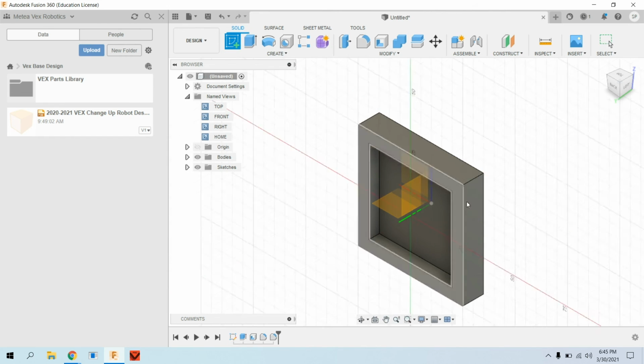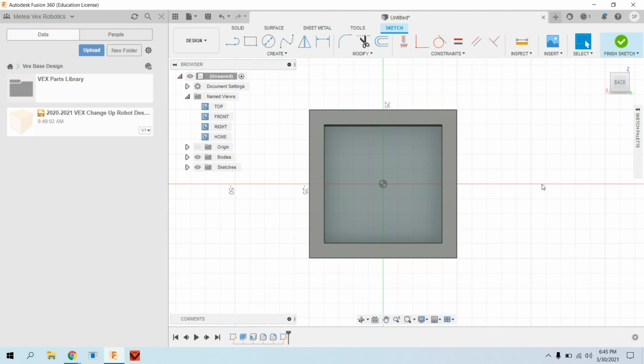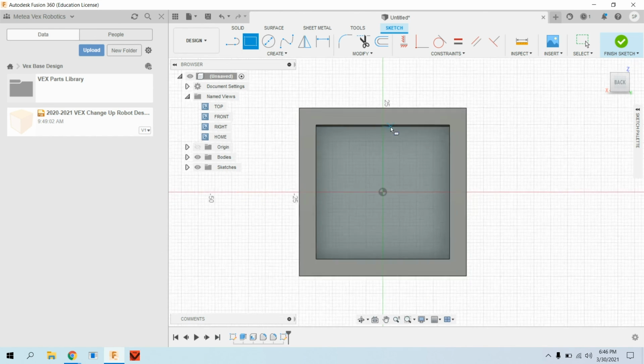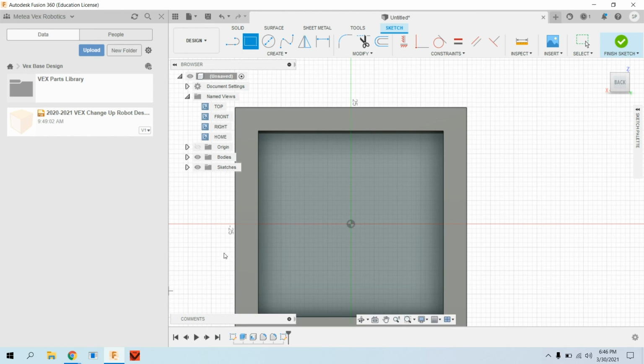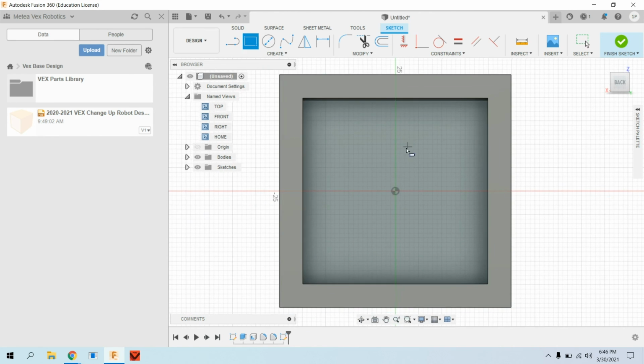Let's say we can create a sketch on this face also. I'm gonna transfer our look into that area. I'm not sure why my fillet didn't work earlier, but we can revisit that after. And then virtually from this point, I can build off of what I have here. So let's say I wanted to make another box, make my box even taller, right? I can start at this point and create a new box. Or I can just create something in the middle here. We're gonna take this point right here. I can scale this all the way out here. Like that, just like that.